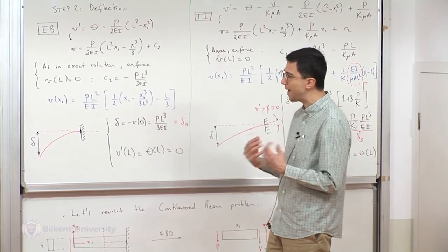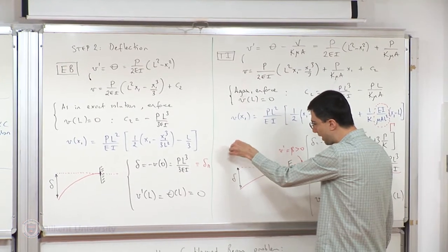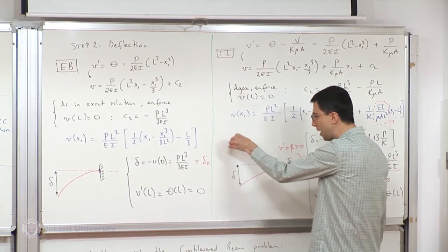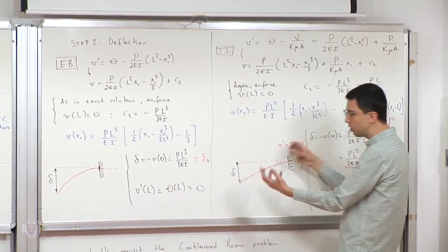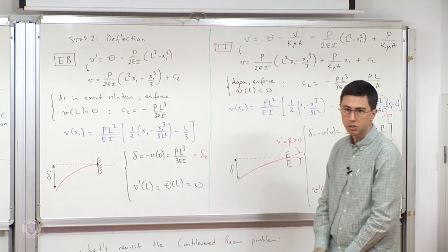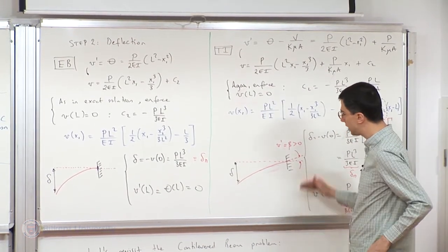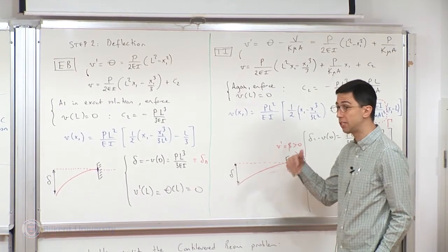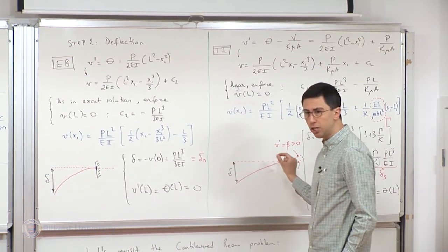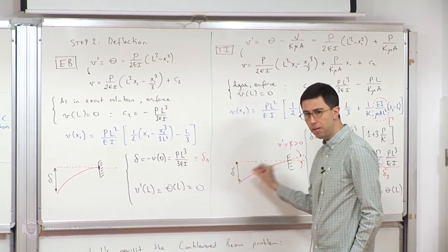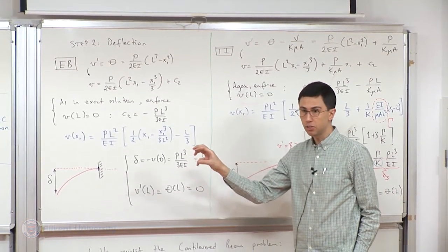So there is also the energy aspect. In other words, if I take a force, I'm applying a vertical force P, and this thing deflects by a certain amount, and this deflection does a certain amount of work. There is a certain amount of energy stored in the beam. Internal energy is equal to external energy input. You can go through that analysis, and eventually what you would like to have as an alternative scenario is that the energy stored in the beam after bending matches the energy of the beam in the analytical solution.